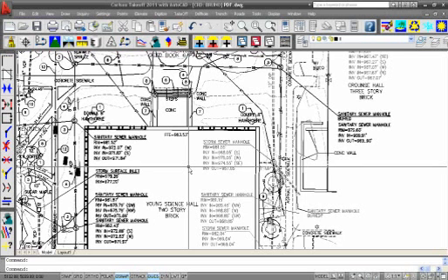It saves you from having to digitize, tracing in the line work, and it comes in not as accurate as the CAD file, but we'll see on this example, it'll save me a lot of time having to digitize and trace really tedious work, digitizing contour lines. But that's based on the fact that we've got elevations in this file. Not on this PDF. You're not getting any elevations. You'll never get an elevation from a PDF file. Okay. But it saves the time of having to trace over the line work.